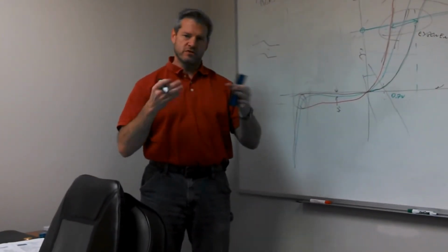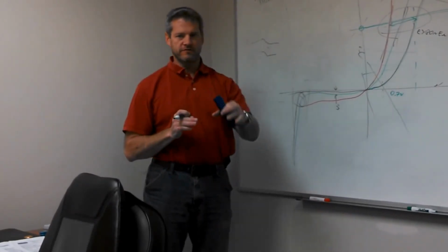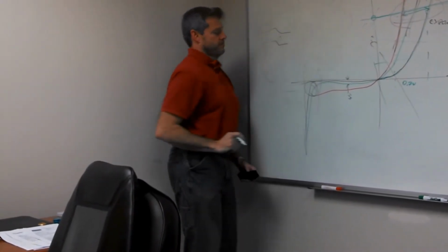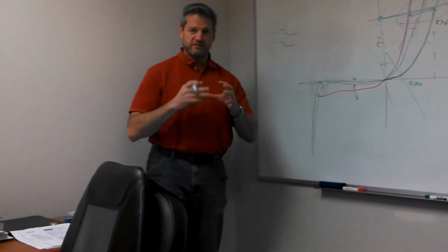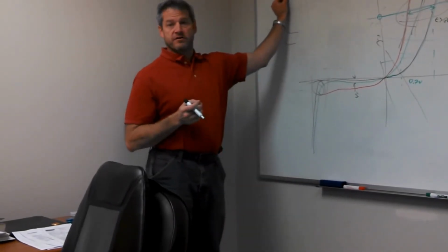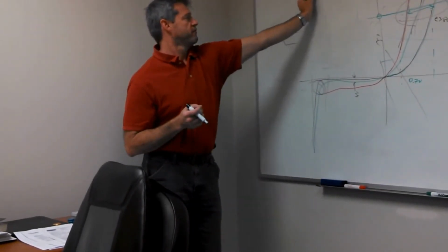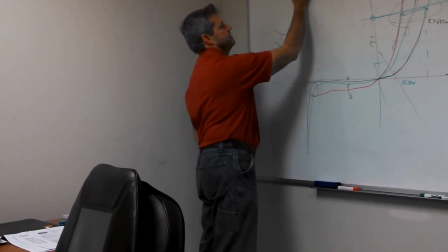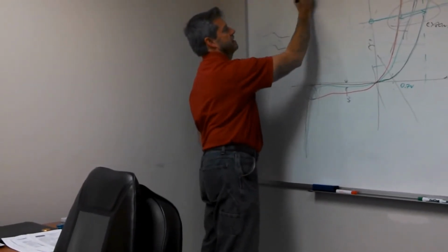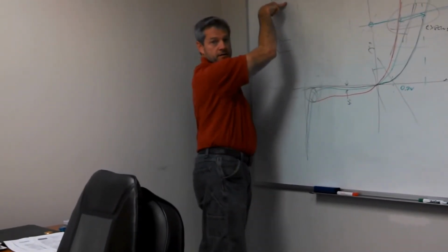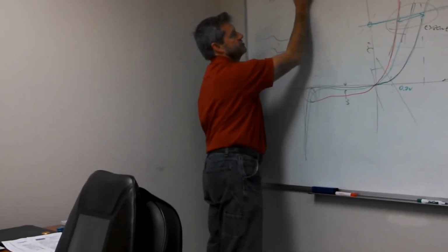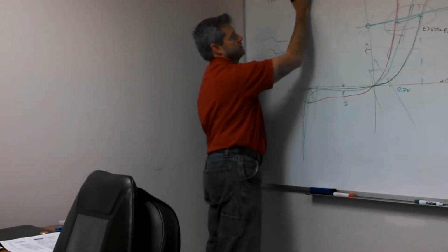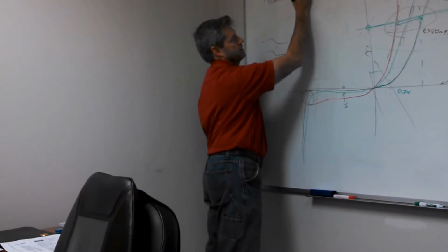They're both statistical, they're both sort of averages. Some will be going a little slower, some will be going a little faster. But what you end up with is a diffusion length right here. So this part of the diode is effectively neutral, and you've created a barrier region there. Now, when I forward bias this, what I'm doing conceptually is pushing positive here and negative here. These holes want to run away, so this region gets narrower, and all my holes are going to be bunching up here, right?